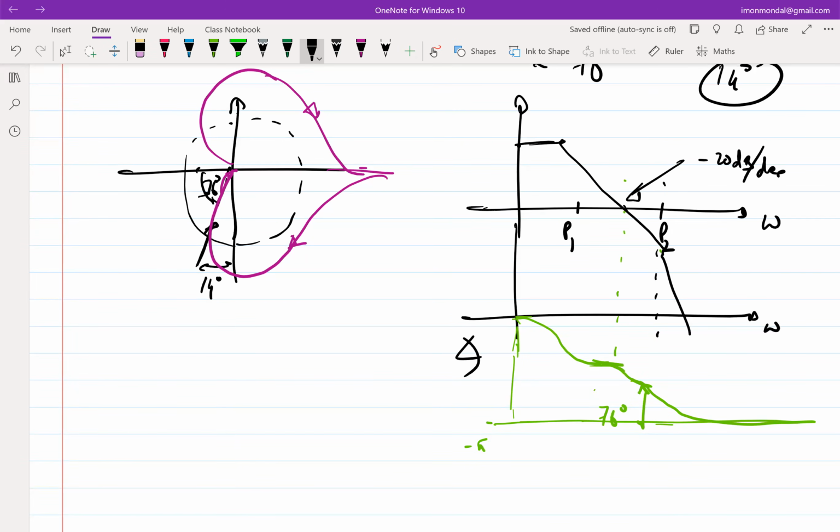But you have to be careful. That's not strictly true. Critically damped is only true for second order systems, but we are trying to get an analogy because ultimately we will iterate, right? Once we develop a system, we put it in a simulator or on a breadboard and we'll iterate, but we need to at least know what to iterate for. So this is what we are going to iterate for. We are going to see the location of the additional poles with respect to omega U loop. If the additional phase from those additional poles is only 14 degree, then I know it's a critically damped system and we are good. Okay.